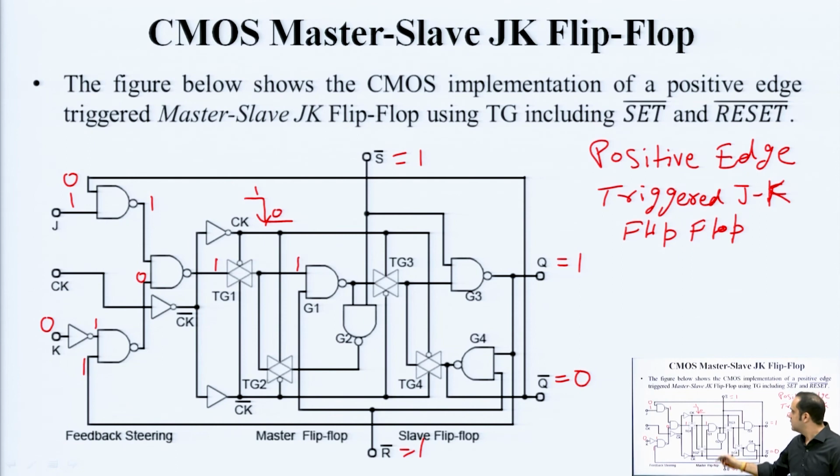they override everything. So, you are getting a 1 here, you are getting a 1 here also, okay, and this one has propagated to this NAND gate here. Now, at the next clock cycle, when there is a positive transition from 0 to 1, okay, and see this logic gate here G1, that has one of the inputs coming from Q. Okay. So, Q is supplying another input through G1 and Q was initially 1. So, both inputs being 1, this will give you a 0 here. Okay. For this logic gate, same with G2, you are transmitting. Now, there is 1 0 here.